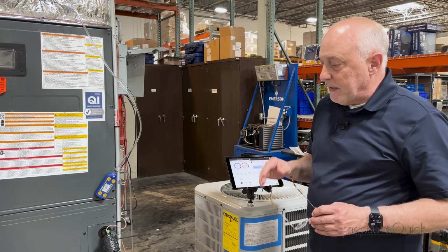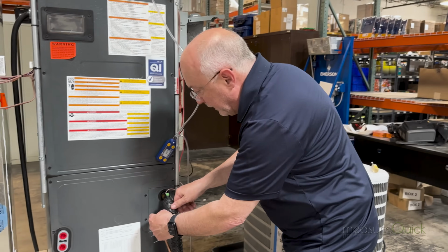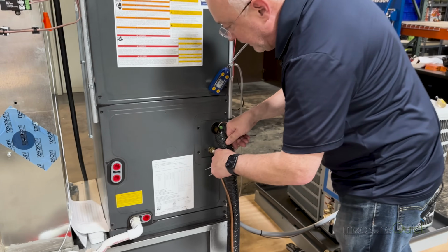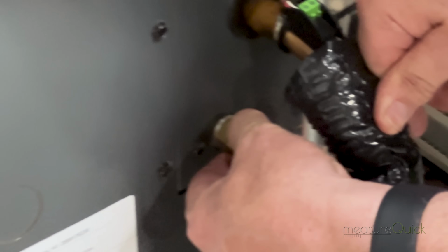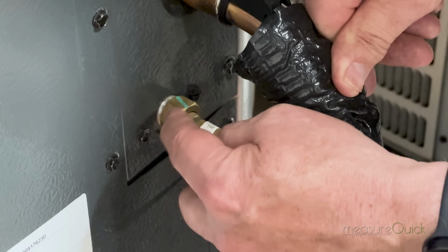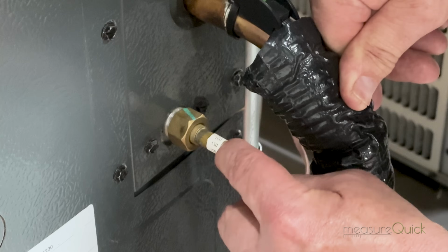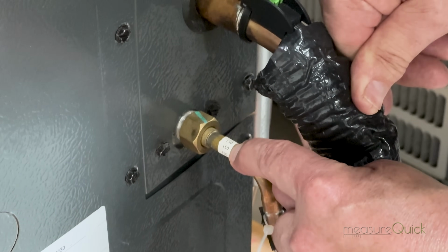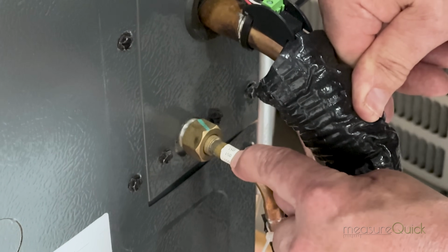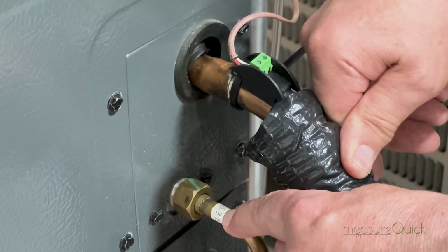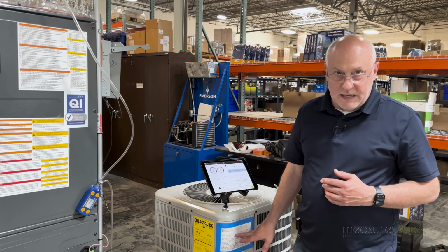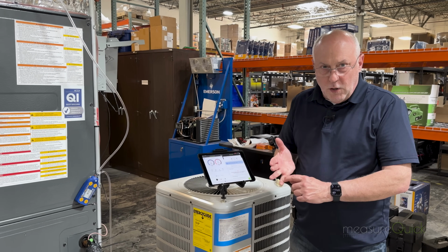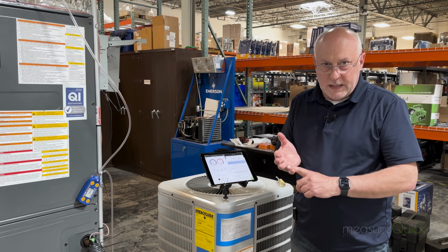Now, this system here, if we look at the air handler on here, this is where the metering device is at, and you can see here that this is a piston. So if this was a TXV, the TXV would be right here, but we also put the label on for the piston. So this is an 051 piston, or 51 piston size on here. And that 51 piston just matches up with this condenser. So we're going to set the airflow and the metering device for the condenser.